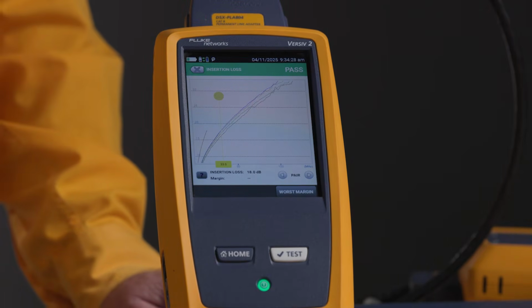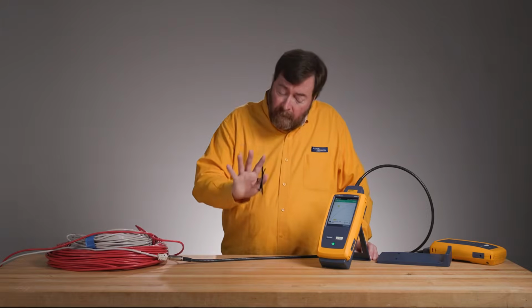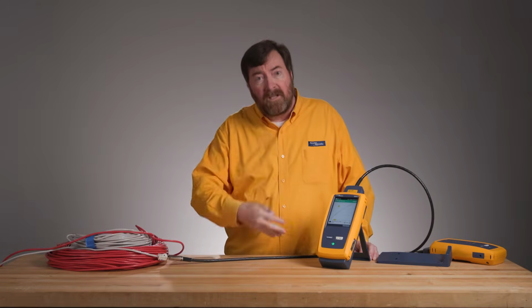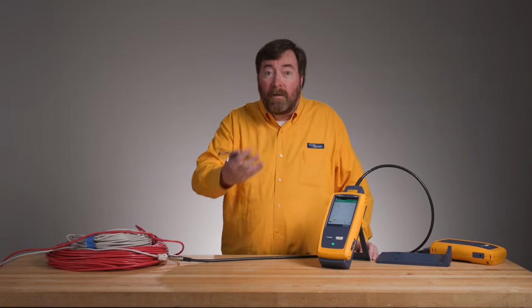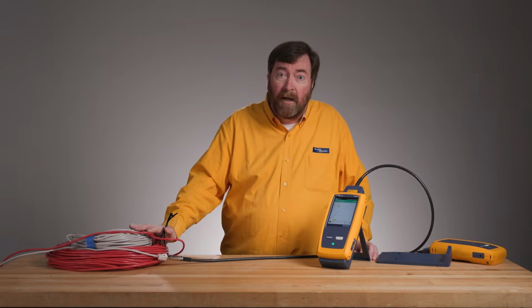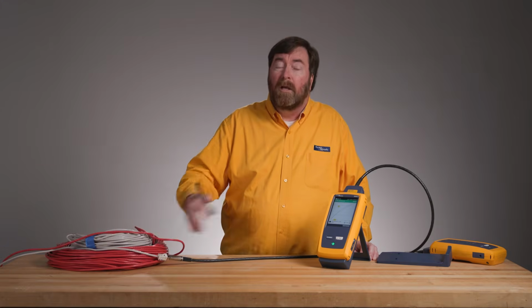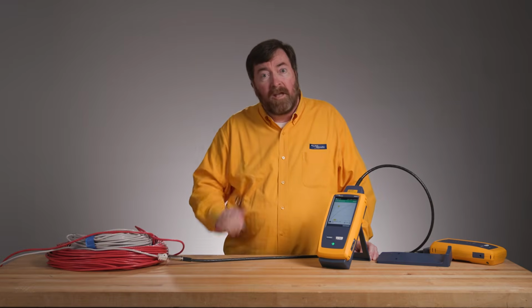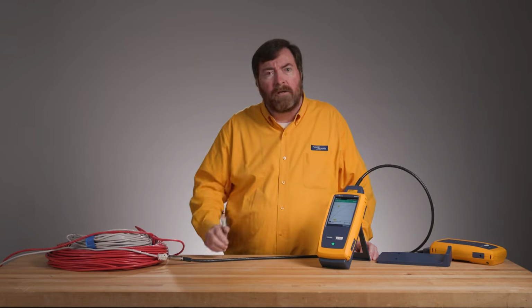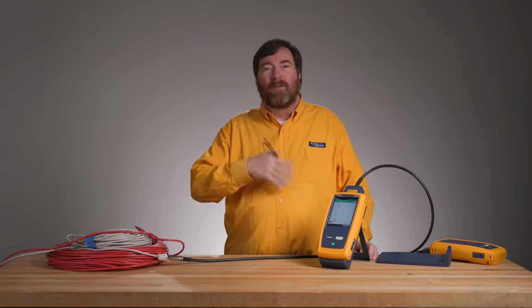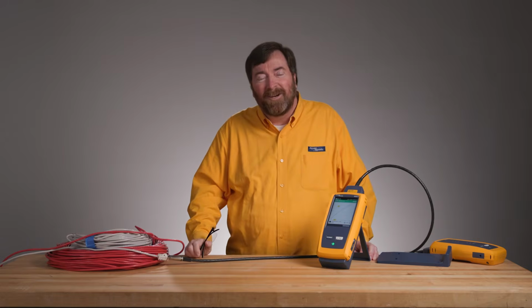So if you're going to use one of these extended limits, remember my personal feeling, I'll get on my soapbox for a minute: follow the standard, install another telco room, or use fiber. But it's not my budget and it's not my application. So if you are going to go farther than 100 meters, work with your manufacturer to make sure you have the right product, the right cable, the right connectors, and you can create an engineered limit for that specific application. There's not a guarantee that it's going to work tomorrow when they come out with a better, stronger, faster camera to put in your parking lot, but it'll work for what you're trying to get done today.